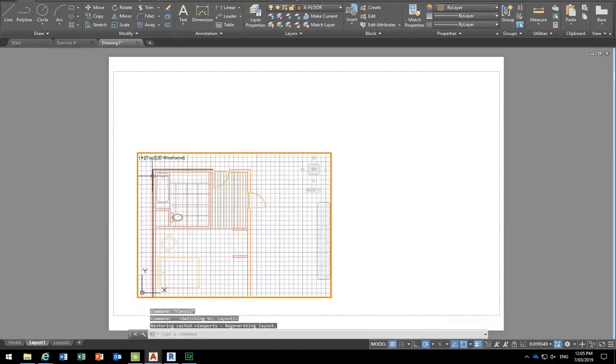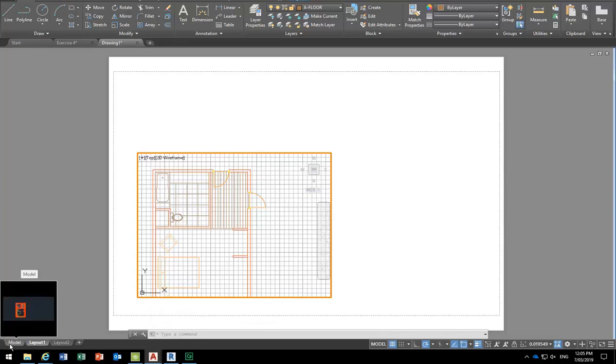Oh, it's really helpful. Sometimes you want to draw on the page. Don't keep adding the things to your plan. Yeah. So you've got those two modes. So when you're drawing in model space, in a viewport, it is just like you're drawing on the model tab. But the limitation is that you can only see what is in the viewport. Oh, normally you would. Often you will just go back to the model tab. But there will be times you'll see later when you want to draw it in the viewport. Yeah. So it's really important when you're working in layouts that you can switch easily between model space, working inside the viewports, and paper space, which is on the page.